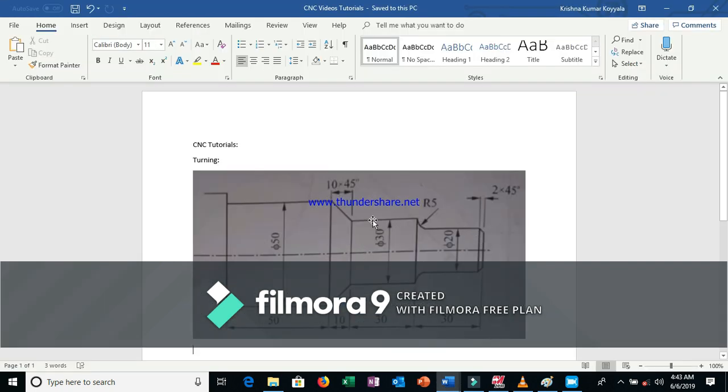Up to this one, here there is a chamfer. So what will they do? First select the line, this is the reference point, and select the point. Make a line with point coordinates. The height on the Y-axis is 25, half of 50. Then horizontally 30 plus 30 plus 10, 70. So minus 70, 25. Give the same coordinates here.